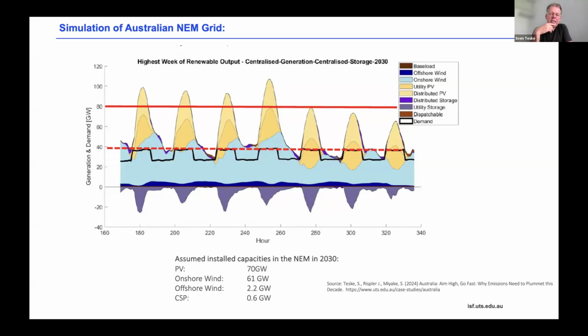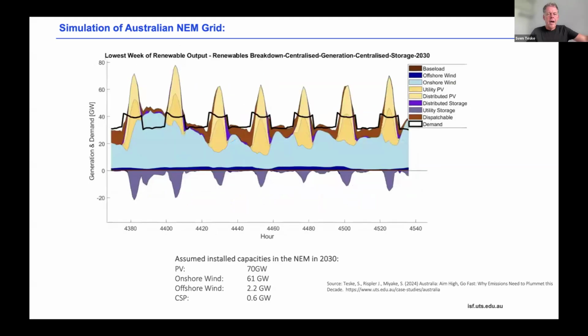And then we have between the two red lines, the minimum and the maximum. So there is quite a bit of peak electricity demand where we need to make sure that we don't run into curtailment. So we have not enough storage capacity. We don't have enough demand. So we basically have to shut down some generation, which will be lost then. We try to avoid that.